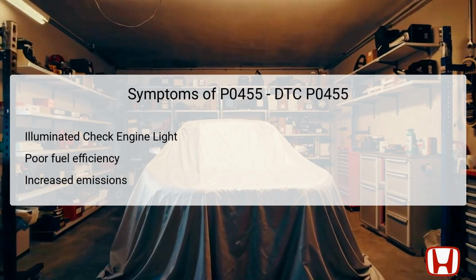Additionally, drivers might experience poor fuel efficiency due to misplaced fuel vapors that disrupt the engine's normal combustion processes. This can also lead to increased emissions, as unburned fuel vapors may escape into the atmosphere. In some cases, the vehicle may show signs of rough idling or stalling, particularly if the EVAP system is unable to manage vapor properly, leading to irregular fuel-air mixtures in the engine.